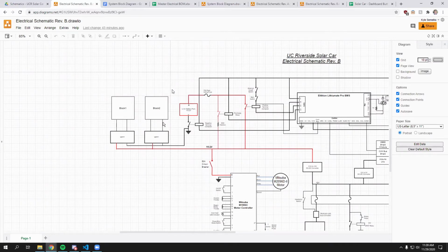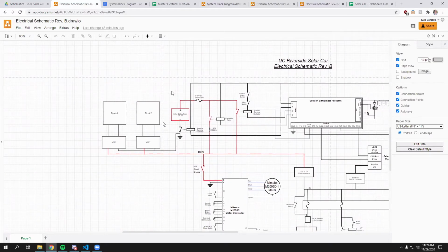However, our sheets are center tapped, which means typically you would only have 2 terminals for each sheet, a positive and a negative terminal, and the rest of the cells you would not be able to access because it's under the encapsulation. But our manufacturer center tapped it, which gives us an extra place to put a bypass diode.